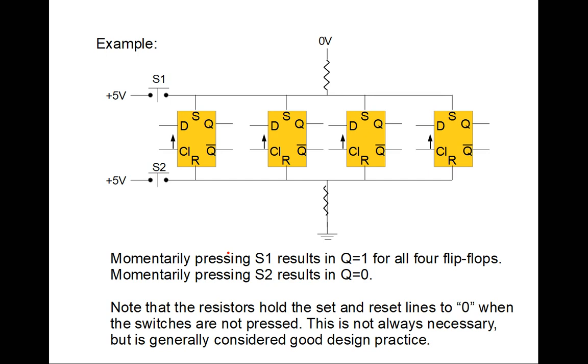And so we can see this in the set and the reset function. We have two lines. This is two wires. This wire is normally 0 because we look at this. There's a resistor that's connecting it to 0 potential. So this is ground. Now, in the event that we press this switch, then this wire is connected. It becomes 5 volts, okay, which of course is a 1.